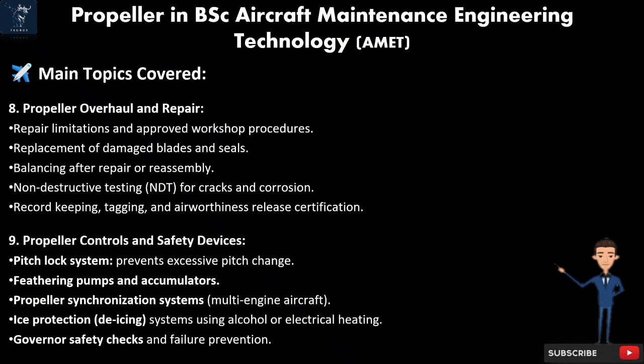8. Propeller overhaul and repair. Repair limitations and approved workshop procedures. Replacement of damaged blades and seals. Balancing after repair or reassembly. Non-destructive testing, NDT, for cracks and corrosion. Record keeping, tagging, and airworthiness release certification.